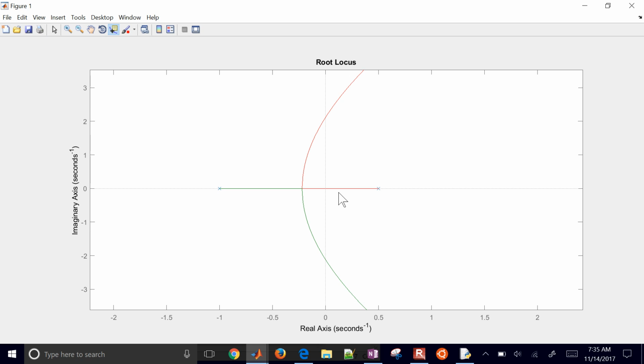So if we have any real parts that go into the right-hand plane, then it's going to be unstable. Okay, and there you can see the gain. We calculated 8.29, and the stability goes onto the right-hand plane right in between those two. Okay, so you can't necessarily zero in right on the value because there's discrete points. But you can see it's going to start oscillating. It's going to create imaginary roots right around a gain of 0.877. Okay, and then you get unstable as well right in between these two.